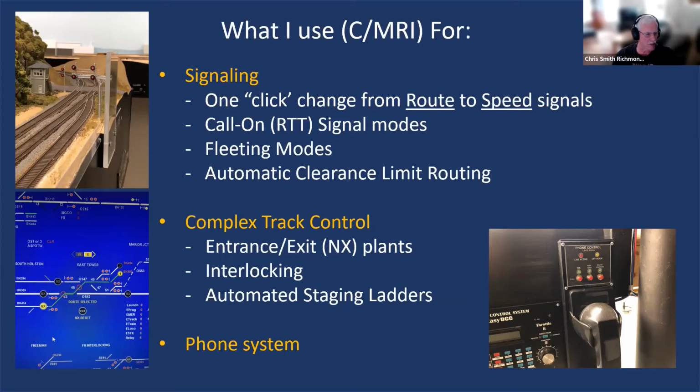the yellow buttons. A train entering from the left needs to go to the yellow button exit on the right. It's an eastbound train, and that's all the dispatcher has to do is hit those 2 buttons and then release the signals, and it will reserve and align that route through the plant. That particular NX has 21 possible routings.